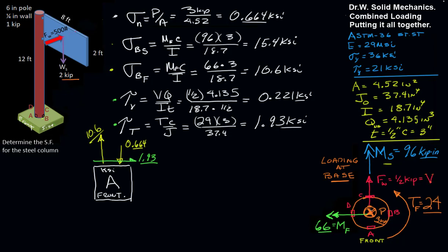So with that, we have all of the stress. And I like to put the resultant values on the other end of the element. So here, acting down, we have 9.94 KSIs. And on the right side here, I can show the other complementary property of shear of 1.93, and those are the net results. And that's just notation to try to keep track of all these values.